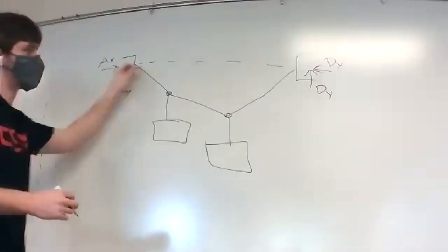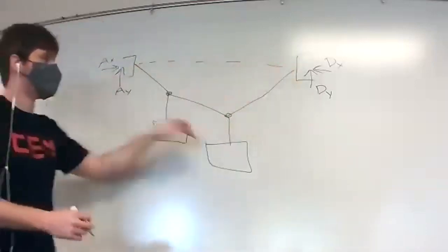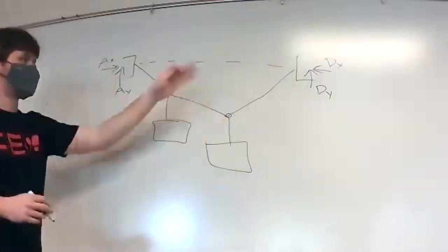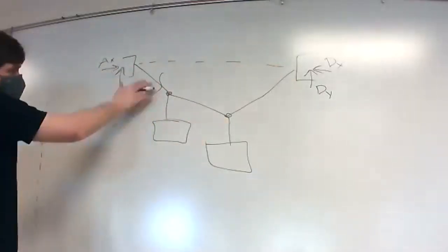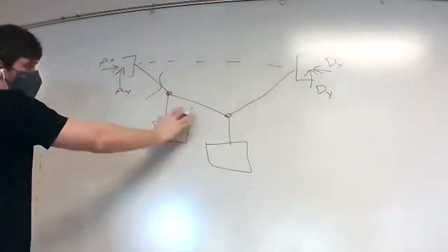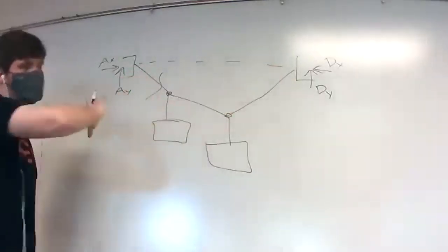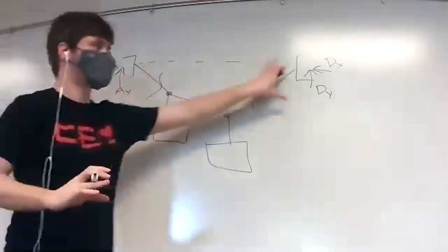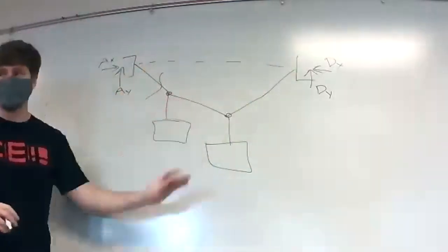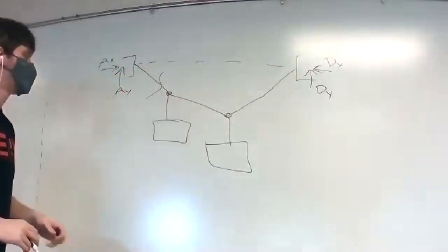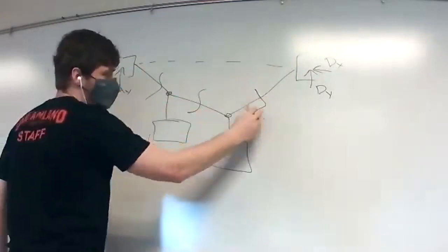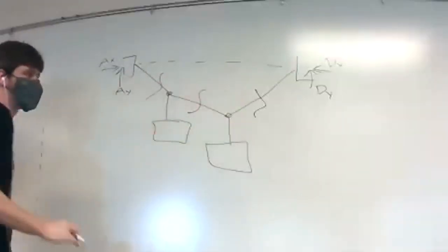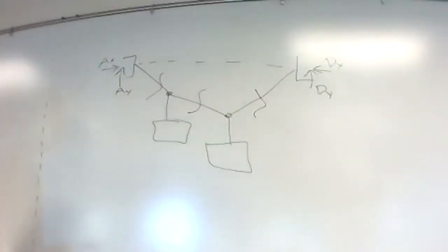Solve this, like this one has it lined up. We could do a moment at A or a moment at D, solve for whichever one we want. Take that cut, say we solved for AY, sum of forces in Y gets us this tension, move on. If we have all these dimensions, super easy. You can just go through the entire cable, summing the forces in a direction, getting your values, and you would take this cut, get this one, move on, take this cut, get this value.